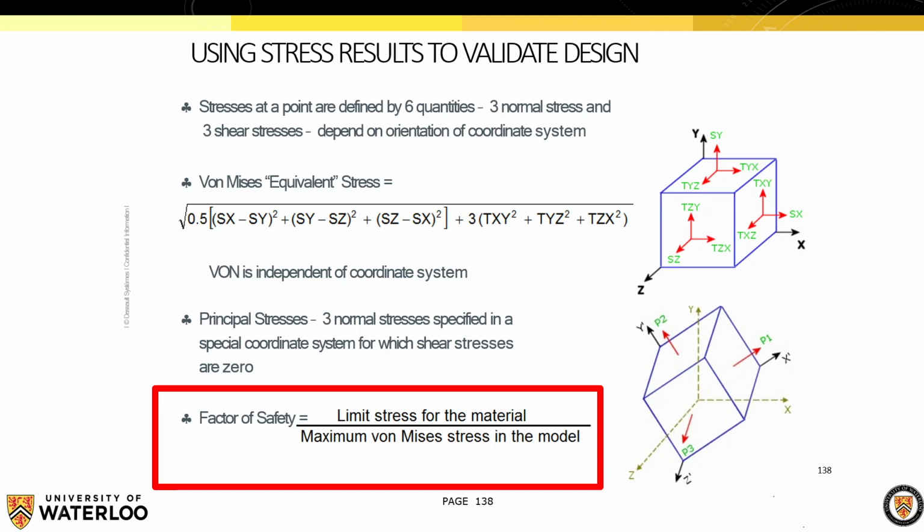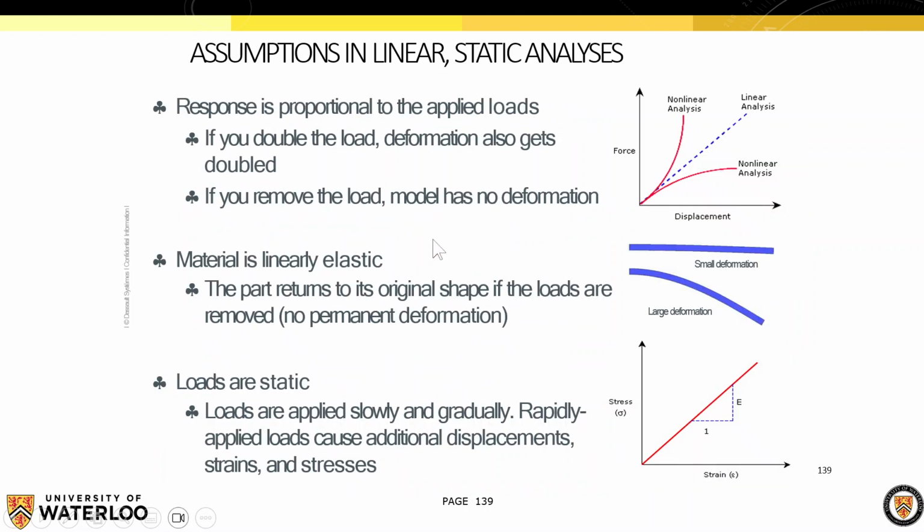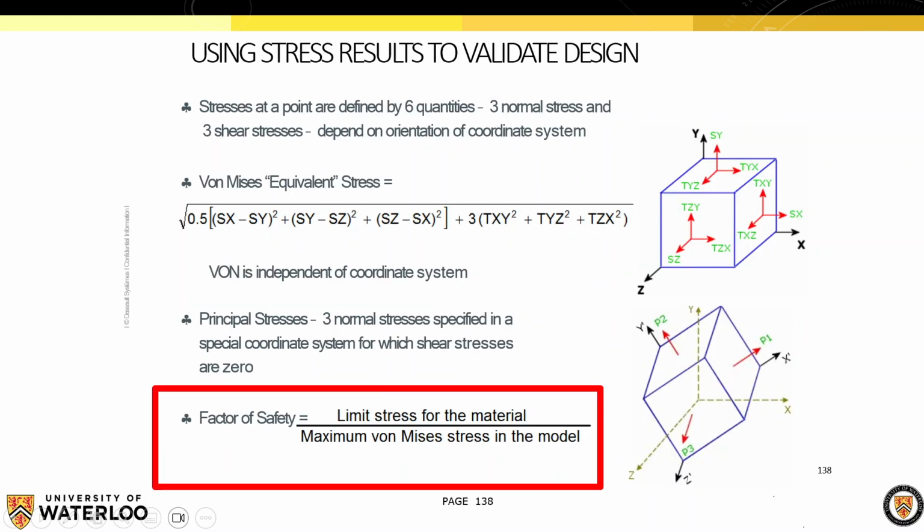The way that we actually look at this is using what's called von Mises stress. That helps us make sense of this complexity by providing a single scalar value of an equivalent stress state. It's combining these tension, compression, and shear stresses into an equivalent stress that has the same effect on the material as the combination of all these stresses.